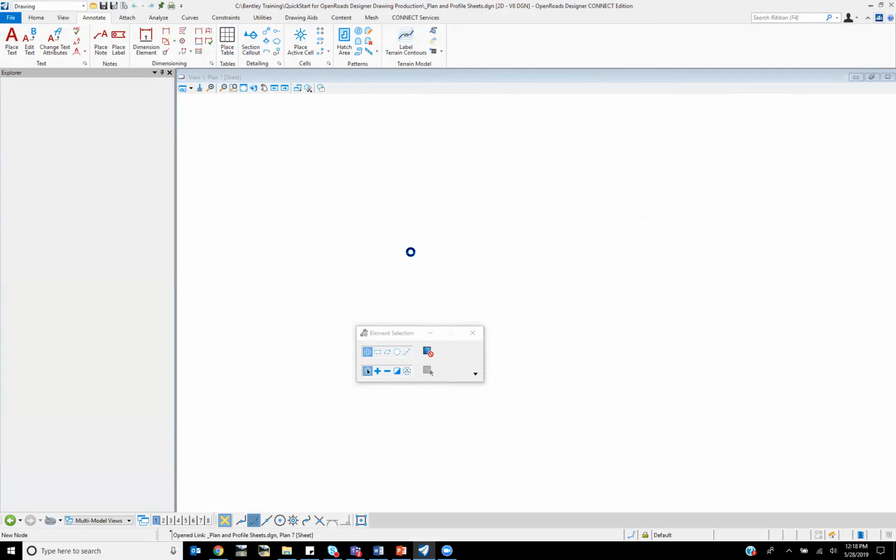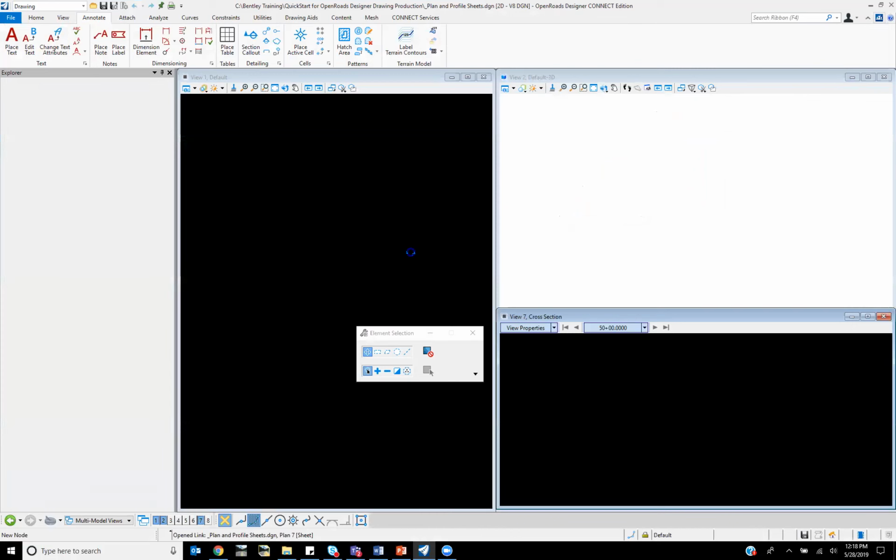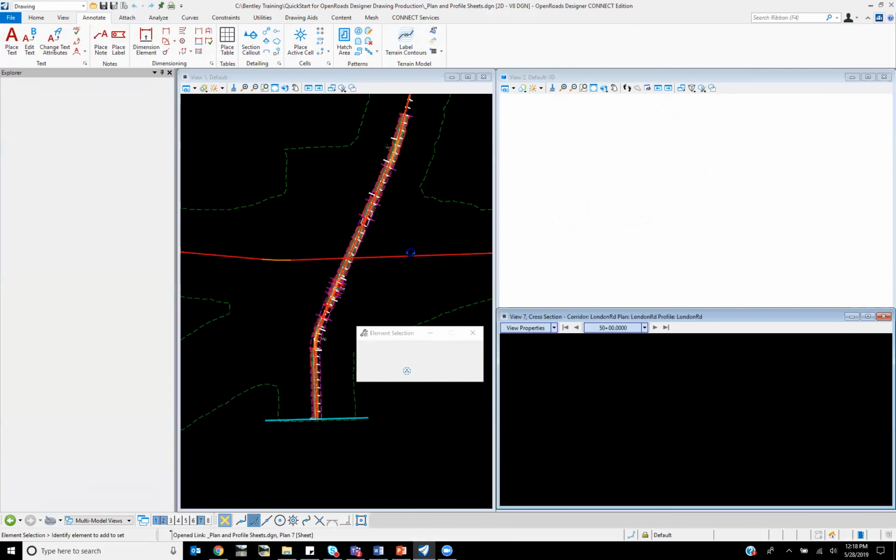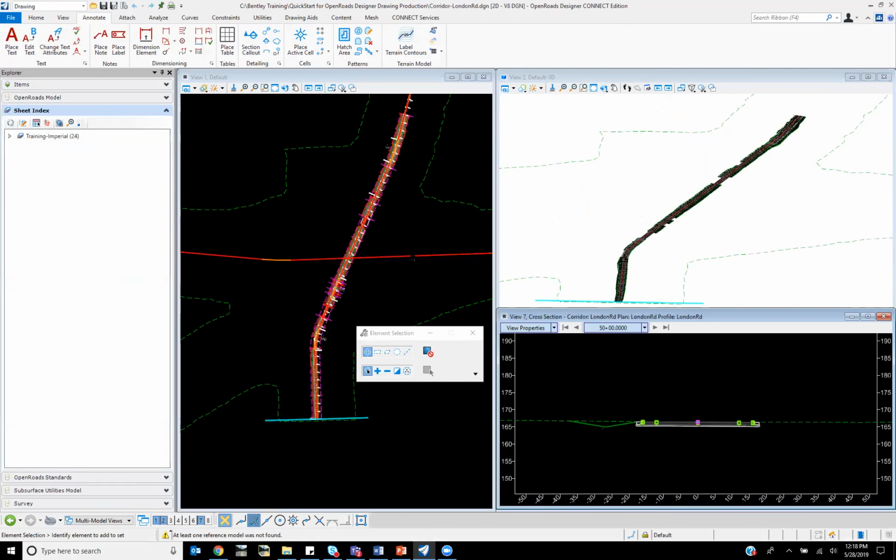Christiana, while you're doing that, we got two more questions. One goes back to the one about not being able to label the surface template. He says we tried it and it would not label slope from a surface template. Okay, so if that's the case, then I'll put my email at the end of this, and you shoot me an email. We'll set a defect number, because it should be labeling those.